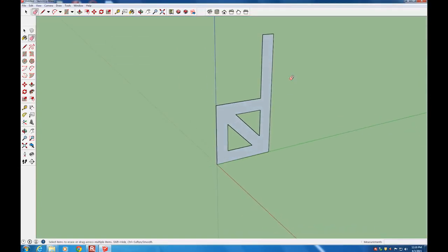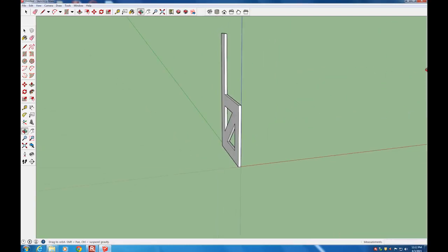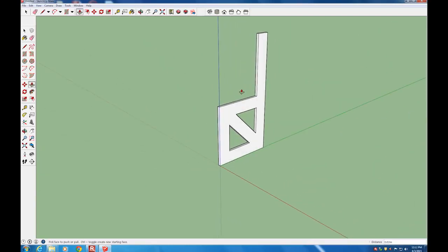And so now I'm going to rotate just a little bit so we can get a better view of the extrude when we do that, and then go over and select from the large tool set the Push-Pull tool, and then hover over the whole face of the chair. It'll highlight blue, and then click and drag the direction we want to go. And we only want to make this 0.02 meters thick. So I type in 0.02 and then enter. And so now our chair has thickness. So we can rotate around, see what's going on. And to rotate, we use the scroll wheel, click and then drag your mouse, and you'll get navigation of your model.